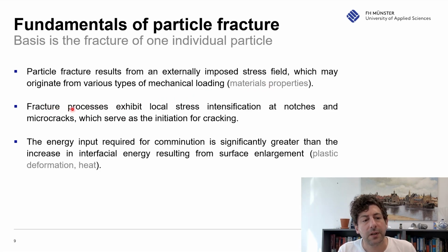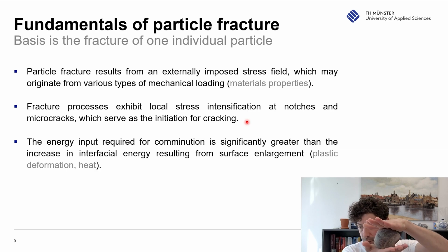And then it's important that the fracture process exhibits local stress intensification at notches and micro cracks, which serve as initiation for cracking. So if I apply a force on this particle, stress lines will go through the particle. And if I have a crack or a hole somewhere, the stress line has to go around the crack in the material.